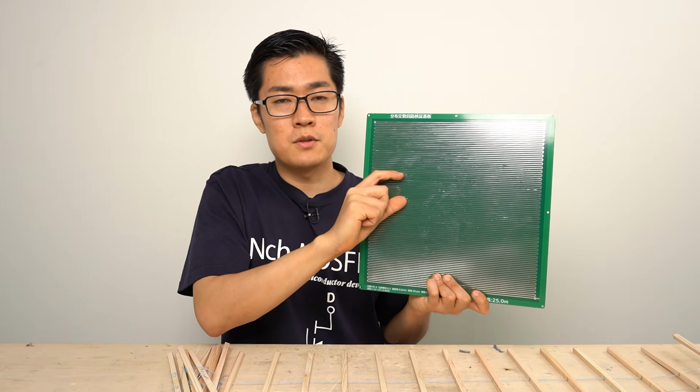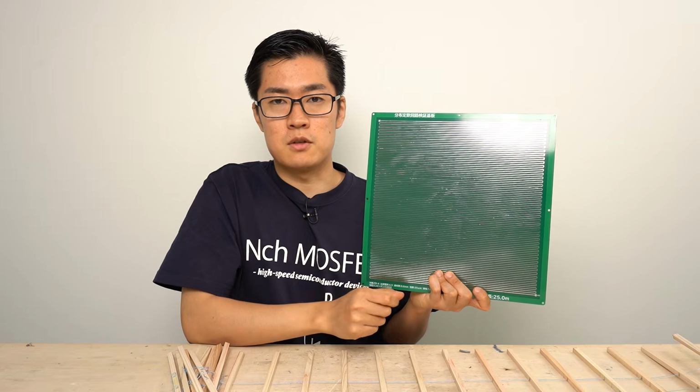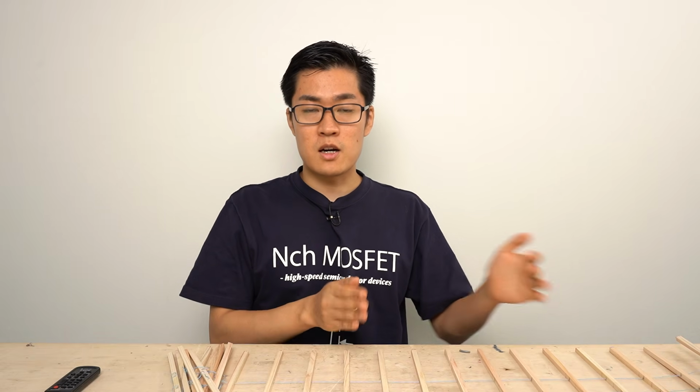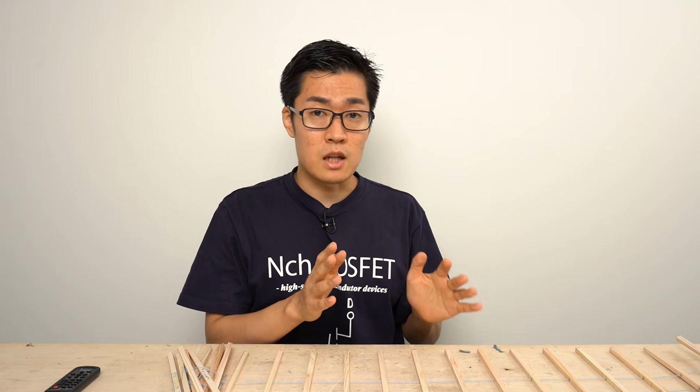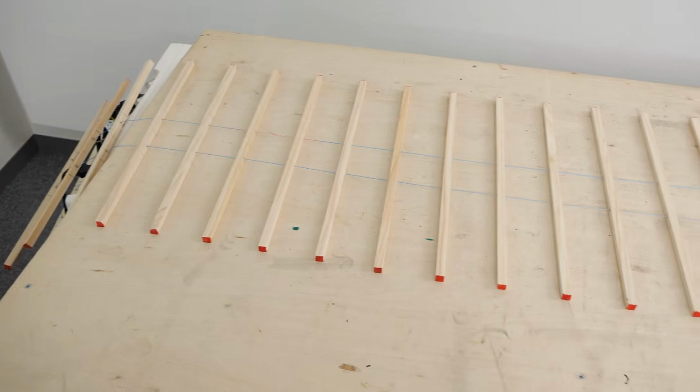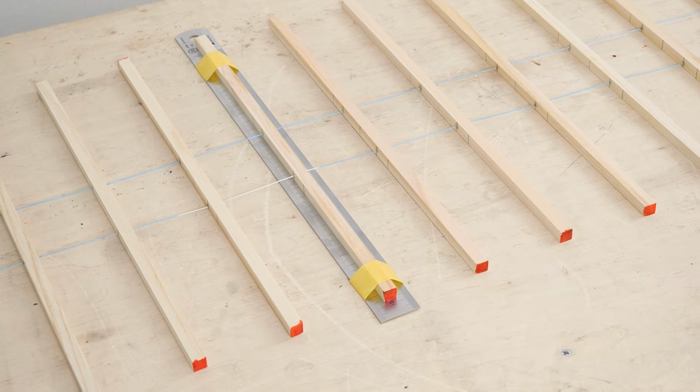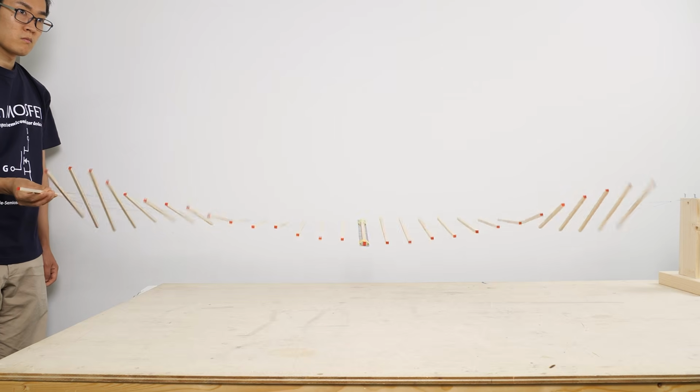For example, if you make a section of the wiring thinner or thicker, impedance matching won't work anymore. Similarly, in a wave machine, if the rod's weight changes partway, the waves get reflected there because the medium changes. For example, if you attach a weight to a rod in the middle like this, the wave changes at that rod. This is the state where impedance matching is not achieved.